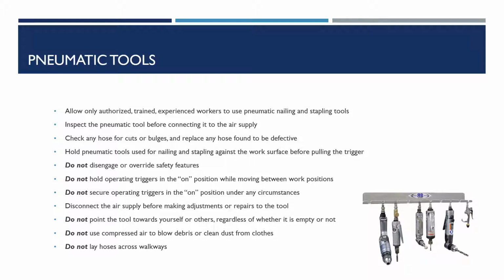Disconnect the air supply before making adjustments or repairs to the tool. Do not point the tool towards yourself or others, regardless of whether it is empty or not. Do not use compressed air to blow debris or clean dust from clothes. And do not lay hoses across walkways.